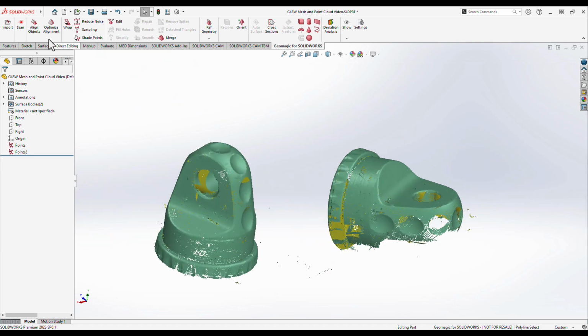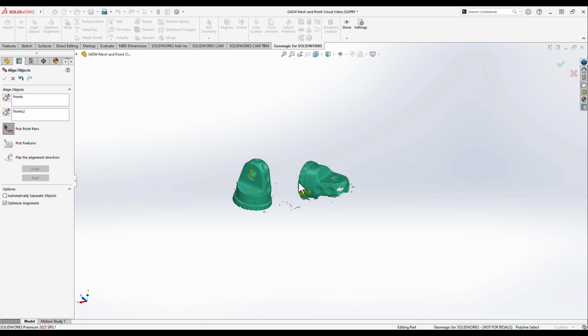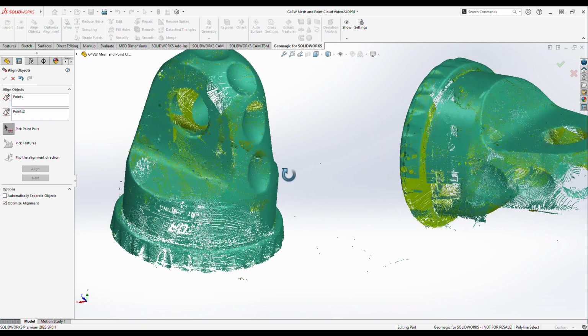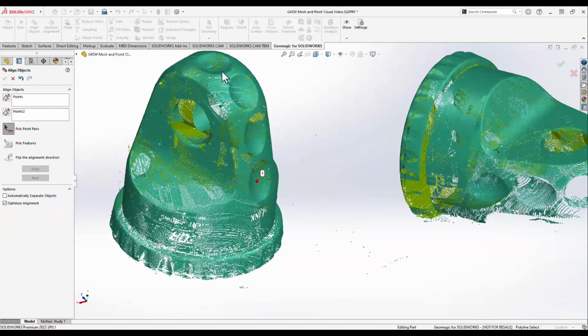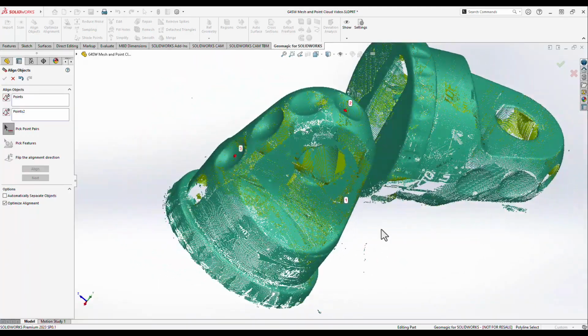Once the data is manually cleaned, the next operation needed for these point clouds is merging. Here, a manual point pairing pre-alignment is used to set things up for a more robust surface best fit algorithm. This gets the scan data into a single triangular mesh model as opposed to the 2 separate point cloud models initially imported.